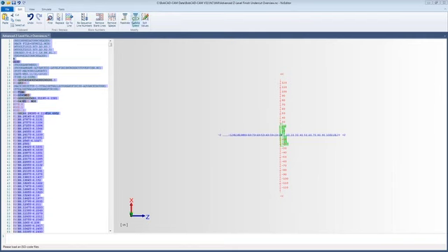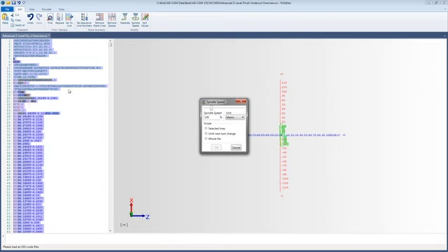Close that off. Spindle speed, same thing. You can go in and tell it what spindle speed you want. It'll find anything with the S for the spindle. S595 here. It'd be able to go in and say, let's go 200% or whatever I end up with. Do the whole file and then hit OK. And there we go. We just doubled that size. So you can change it right on the fly in there.